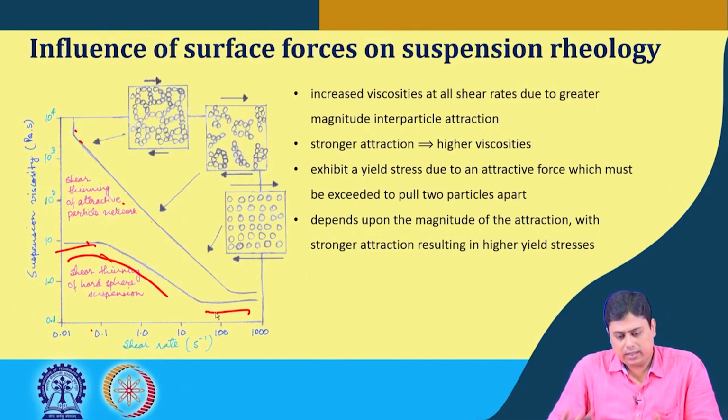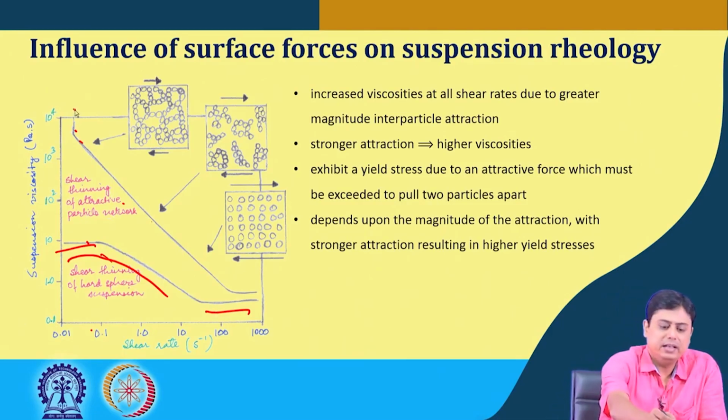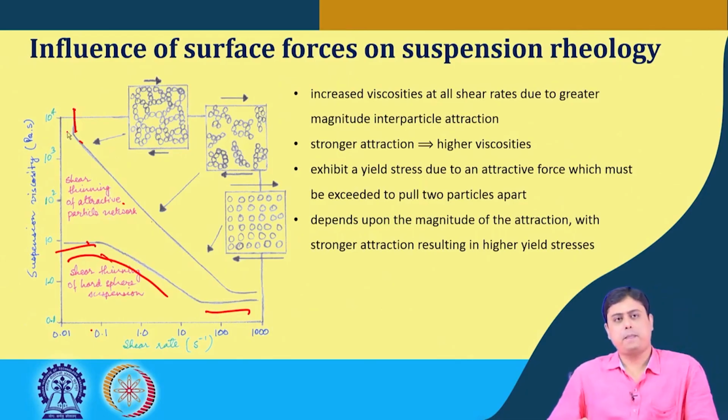The stronger the attraction, the higher the viscosities, and sometimes it exhibits a yield stress due to this attractive force, which we have to exceed in order to pull two particles apart and break that bond. This is the yield stress behavior. A stronger attraction results in a higher yield stress.